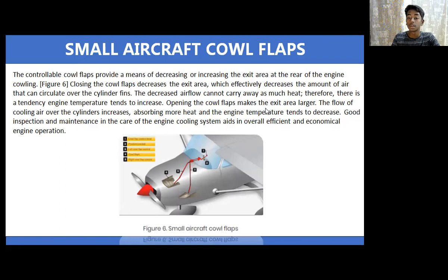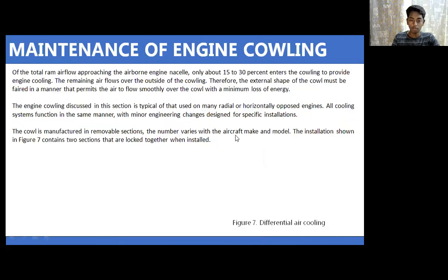Opening the cowl flaps makes the exit area larger. The flow of cooling air over the cylinders increases, absorbing more heat, and the engine temperature tends to decrease. Good inspection and maintenance in the care of the engine cooling system aids in overall efficient and economical engine operation.